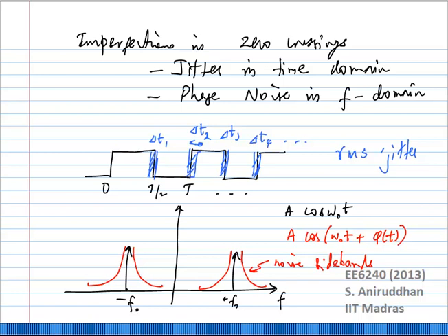As it turns out, the amplitude of the oscillator is intimately tied in with the noise performance of the oscillator. What kind of noise are we talking about? Because we don't worry too much about the amplitude, and the mixer is interested only in the zero crossings, we are primarily interested in imperfections in the zero crossings at the VCO output.